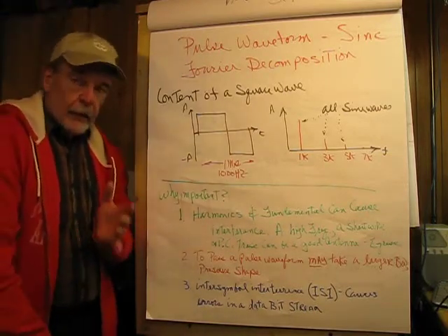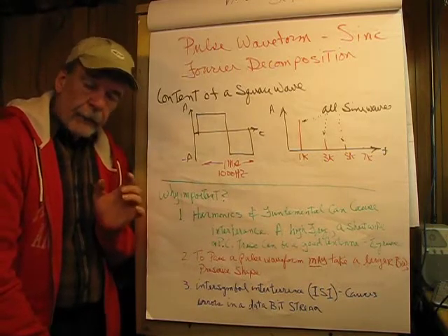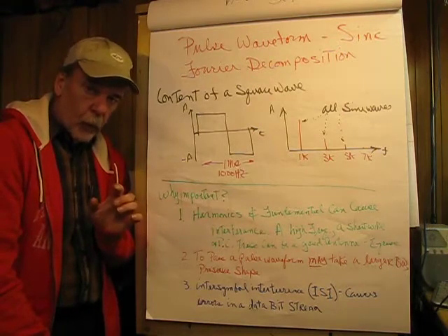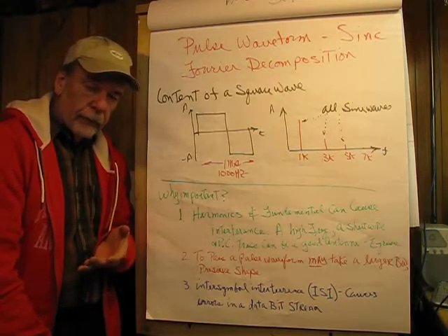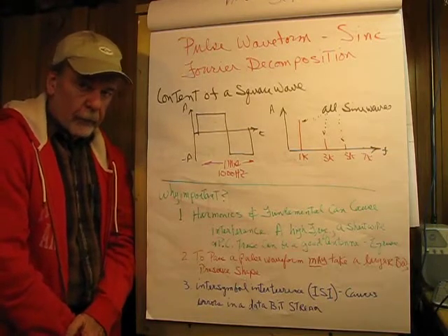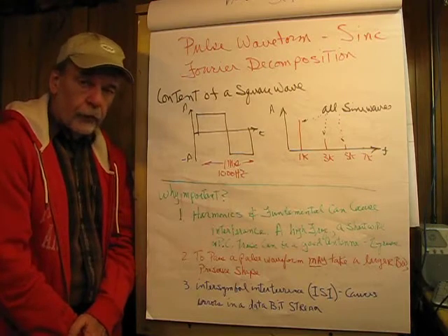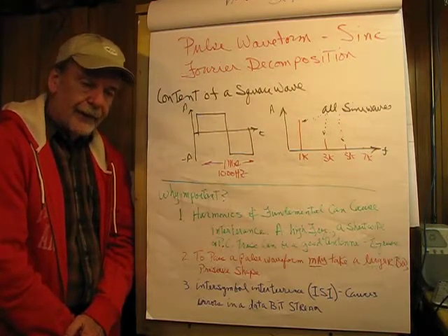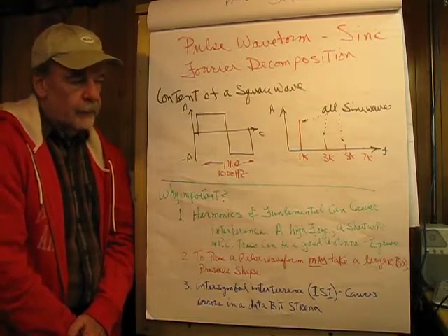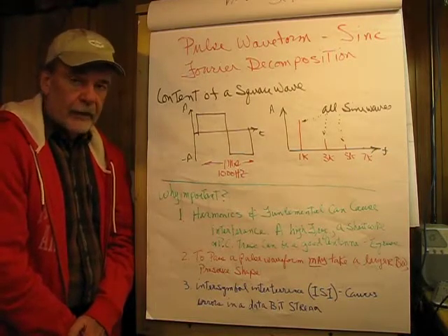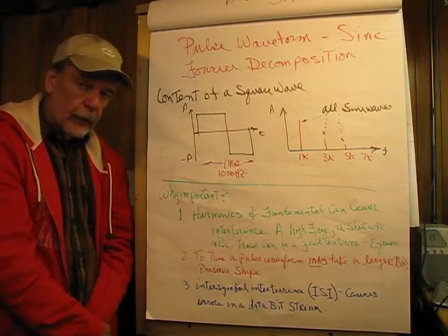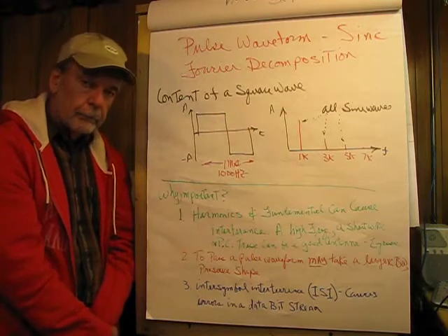The thing is that if you have high frequencies, it requires a small antenna, a short piece of wire, to be effective. You might notice that your cell phone doesn't have an antenna protruding from it. The reason is that the frequency is so high that a small antenna inside the cell phone is quite effective. So we may be radiating energy, even though we don't intend to, by having sharp edges in signals in the equipment we work on or design or repair.